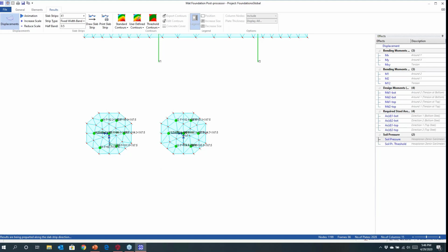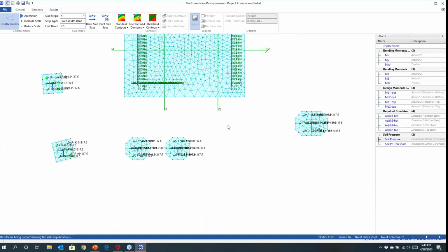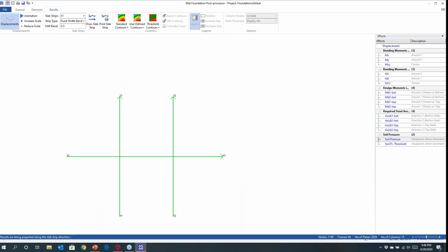Okay, and that's not always ideal and what you'd like to achieve with, say, a pile cap design. So we don't typically use these here, but if you had a very irregular pile cap shape, you could define that, you could define the piles within that, and then you could use finite element analysis to consider the design of that.